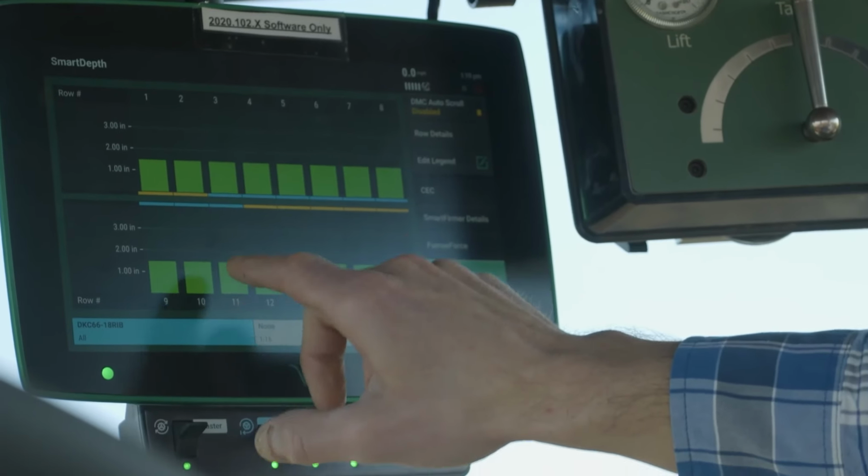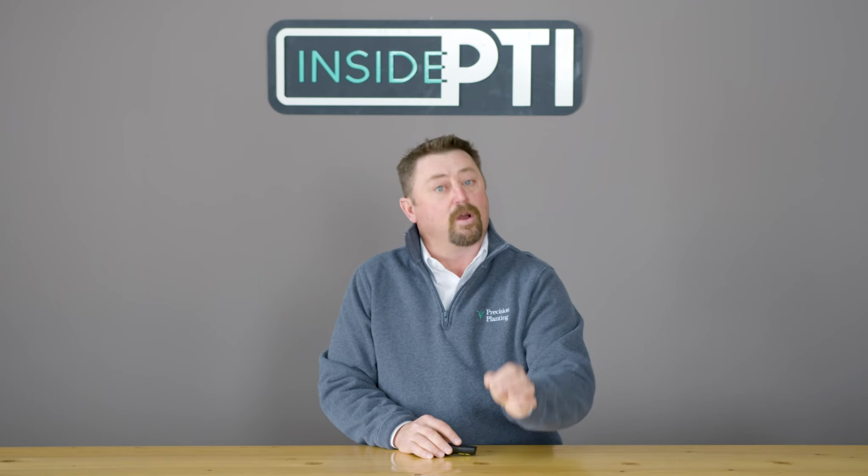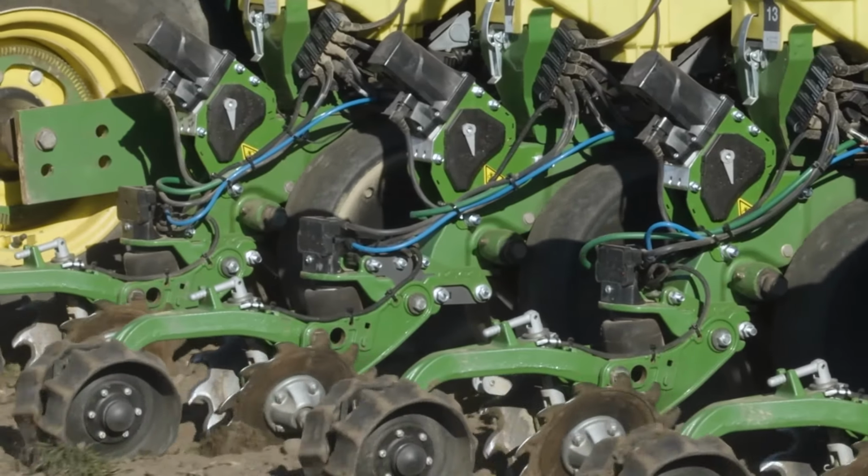This is interesting to me because the first time I ever used this in the field, I go to the 2020 and I've got a depth button on the monitor now. I got a monitor system that tells me how deep I'm planting corn, and that was very reassuring. It also shows me the depth of every row as I'm planting through the field. Again, that is assurance that if you want to plant 2-inch depth corn, we're getting 2-inch on every single row of the planter.